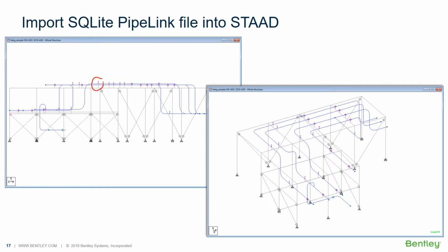You have to work around something, or whatever the situation is. If you have a situation like that, you can come into here and actually change the connection. It doesn't have to be what is automatically decided as the most sense by STAAD. So you want to review them and make any changes that are necessary